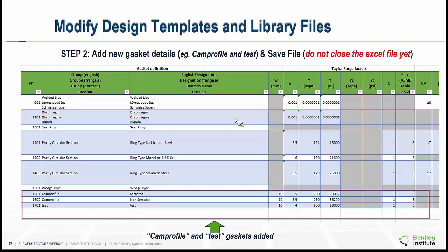Yes. Okay, great. Another one, can you export the nozzle local loads for analysis by a third-party software? Yes, nozzle local load you can analyze. First of all, I would like to say that you can apply all the different local load methods, WRC, PD5500, GOST, all those methods you can apply, EN also. So if you want to export nozzle local load, for example, to Nozzle Pro software, you can do that through the nozzle local load tab of the nozzle section.